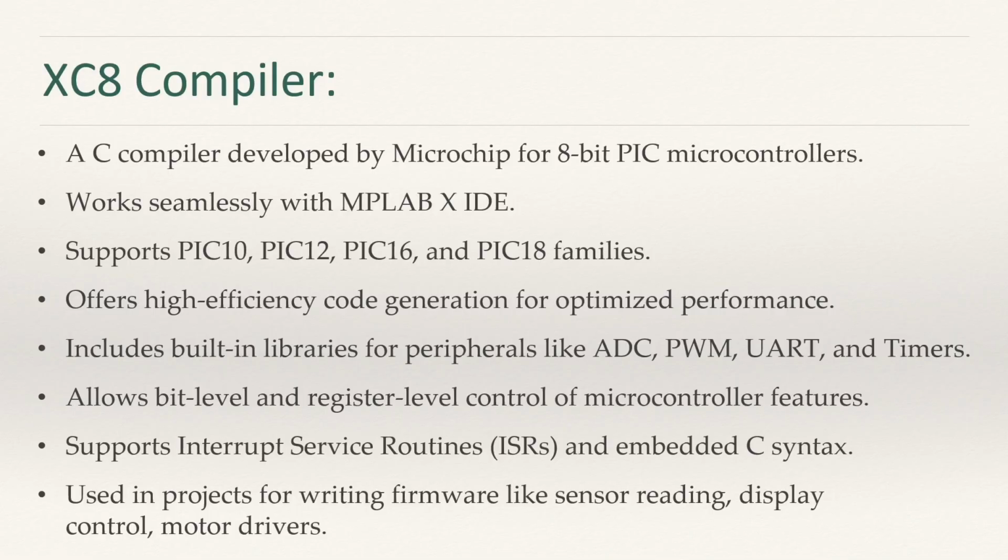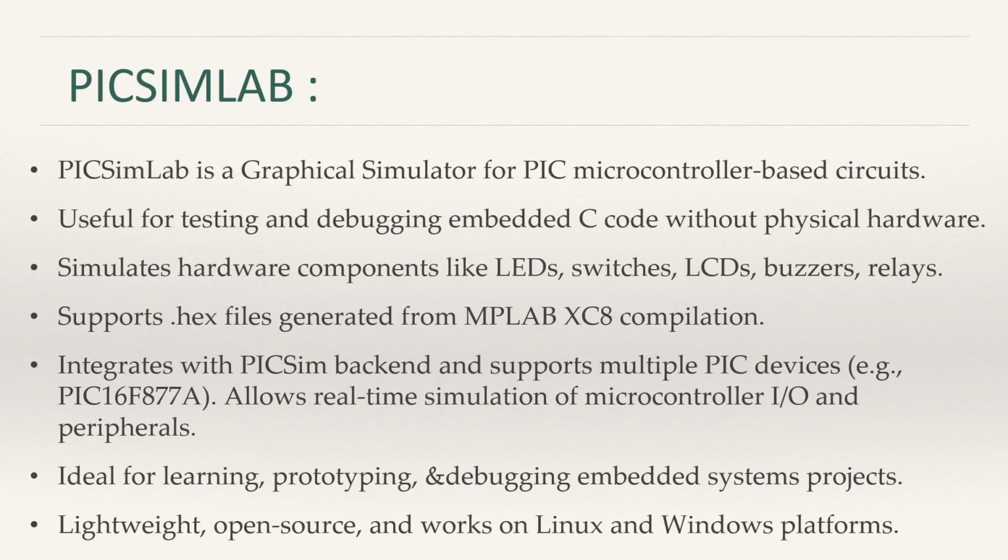It includes built-in libraries for peripherals like ADC, PWM, UART and timers. It allows bit level and register level control of microcontroller features. It supports interrupt service routines, ISRs, and embedded C syntax. It is used in projects for writing firmware like sensor reading, display control, motor drivers.